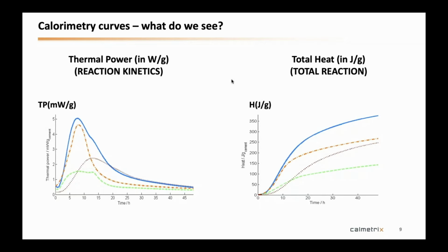One thing you have to see and understand about calorimetry, the beauty of it, is that you get a continuous curve. You get from time zero of the reaction until the time you want. You can get a picture of everything that's going on in there. There's hardly anything else in your testing equipment that does that. XRD doesn't do it. Physical testing, like compressive strength testing, doesn't do it. You only have results at certain points in time with those methods. With calorimetry, you actually have a continuous curve. And that's a beautiful thing, because you can see how the reaction evolves, especially for the kinetics.